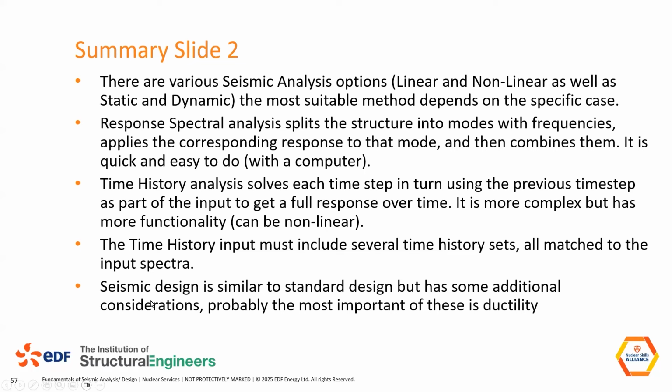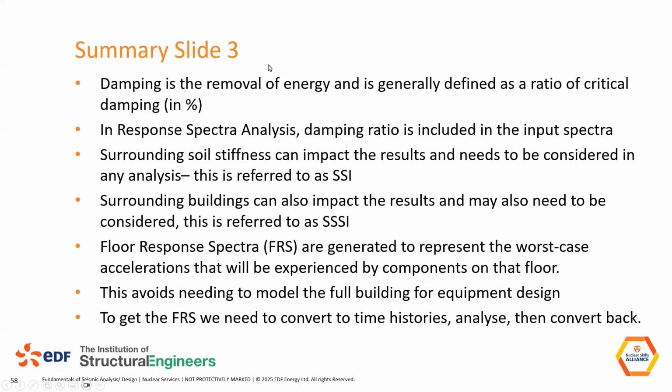For seismic design, it's not that dissimilar to normal design, but there are ductility requirements which set reinforcement, detailing arrangements, and connection design, etc. There are other aspects, but the most important is trying to ensure we have a ductile failure mode. Finally, on the last three points, damping is removal of energy. We define it as a proportion of critical damping. For response spectra analysis, it's defined in the response spectra itself, so that sets the damping. In time history, you can assign the damping to the elements, and you can vary it with elements.